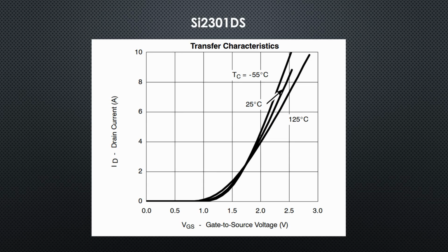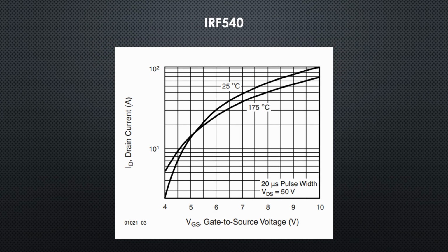in the catalog. The best way is to go to the datasheet and search for the diagram which shows ID in relation to VGS. Select the curve for 25 degrees Celsius and check where it starts. If it starts below 3 volts, this is an indication that it is a good choice. The IRF540 I have used before is not a good choice, as we easily can see in the diagram. At the Arduino 5 volts, it conducts 20 ampere, but below 4 volts, nearly nothing.